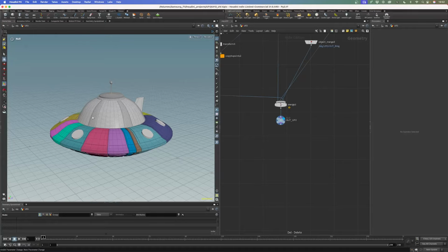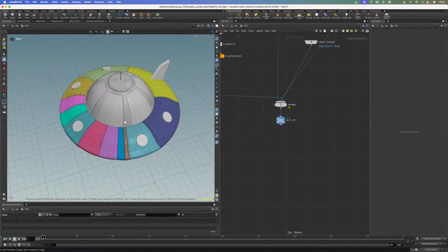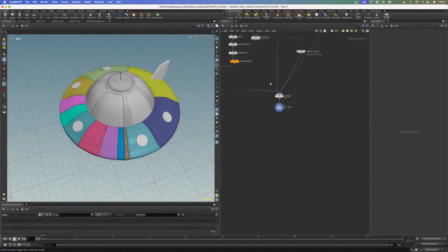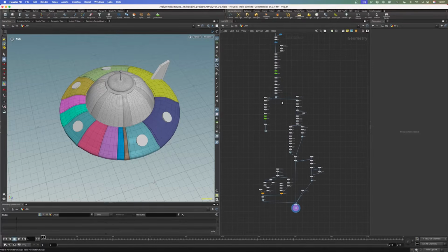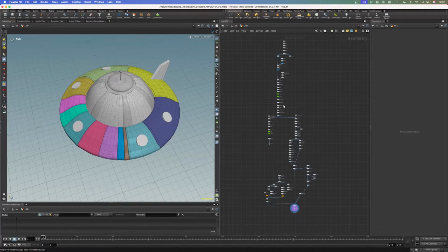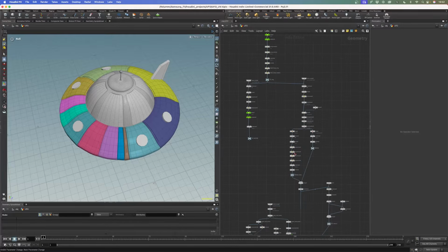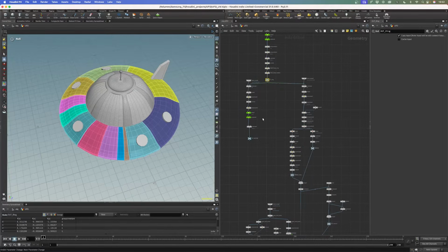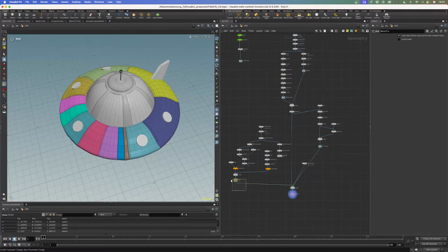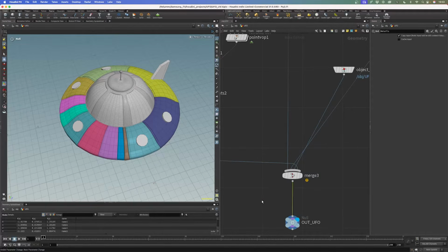For a complex object like this, I would divide it into parts, and looking at the node tree here, I would always think about UVs while I'm building a geometry. Once I come close to the end of a section, so basically everywhere where I put in null objects, I would already calculate some UVs for the specific section, which are then getting merged right before the end, and then we are going to append a UV Layout and everything gets distributed quite nicely.